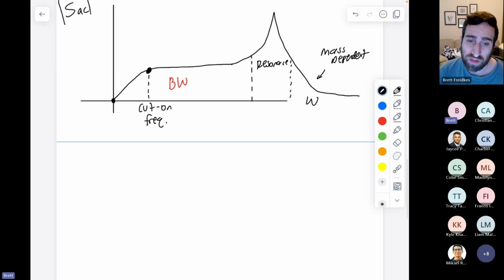But just to remind you while they're typing, there are 2 ways to really go about this. We have this long expression for sensitivity that we derived last time with current division, and we can plug in omega is 0 and see what happens. We can plug in omega equals omega n and see what happens. But another thing we can do is take the circuit that we drew and redraw it in such a way where we will neglect things depending on the frequency.